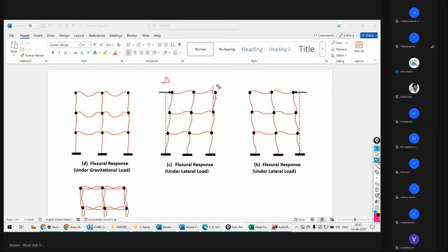So for this small delta, this column is going to be designed, and this entire structure means that entire stress is going to be subjected to the base of your structure. सारा स्ट्रेस आपके बेस पर ट्रांसफर होगा ग्लोबली, that is what p big delta effect, and each individual member is shifted from its original alignment, actual alignment.